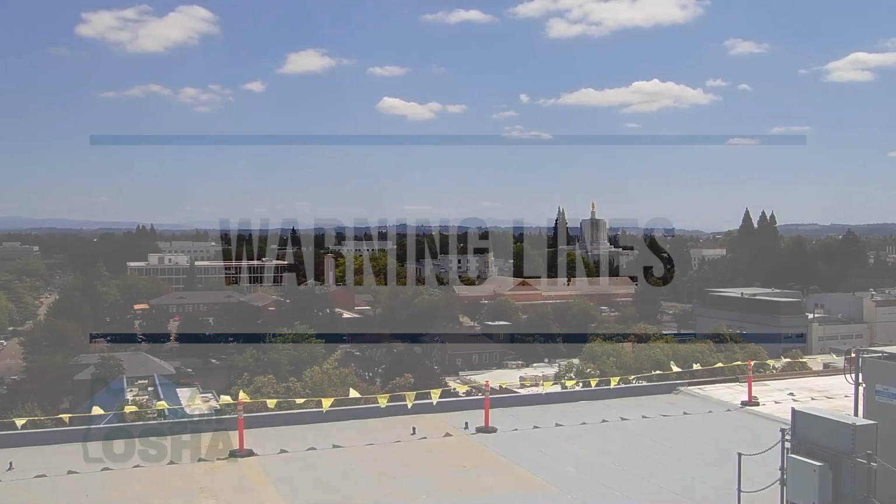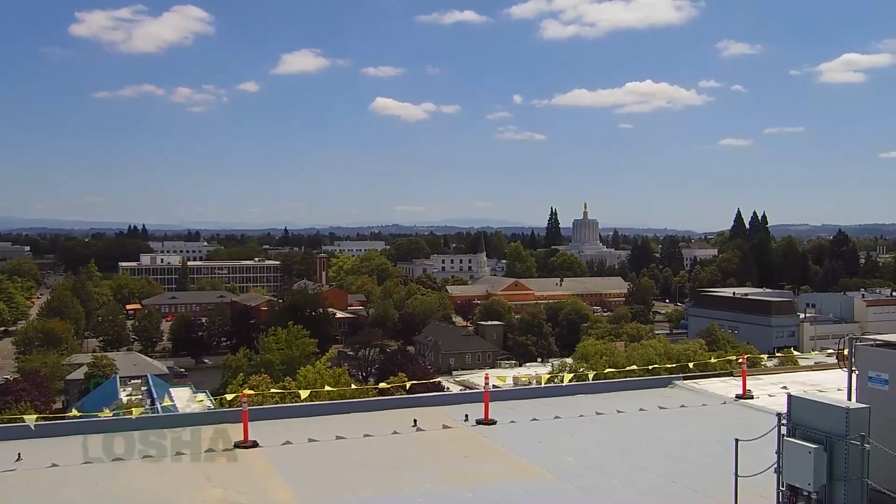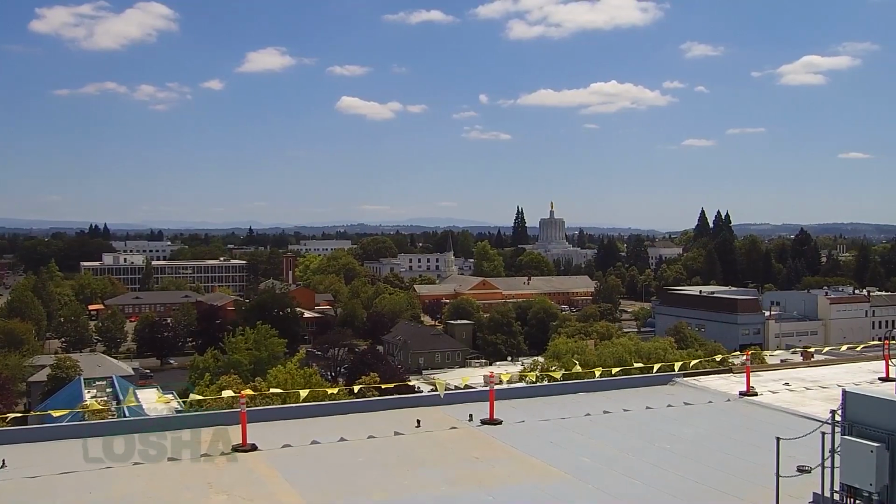The idea behind the warning line system is just to make sure employees are aware that there's an edge there. Once you get up to a certain pitch, you can't use them anymore because obviously it's not going to stop anybody from falling off, right? Just like in the term, it's a warning line. It lets them know, hey, there's an edge here. In case you were backing up and weren't paying attention, you need to stop and check your surroundings out.